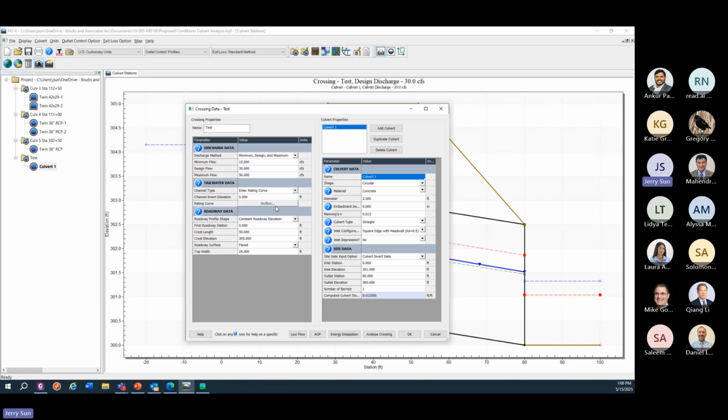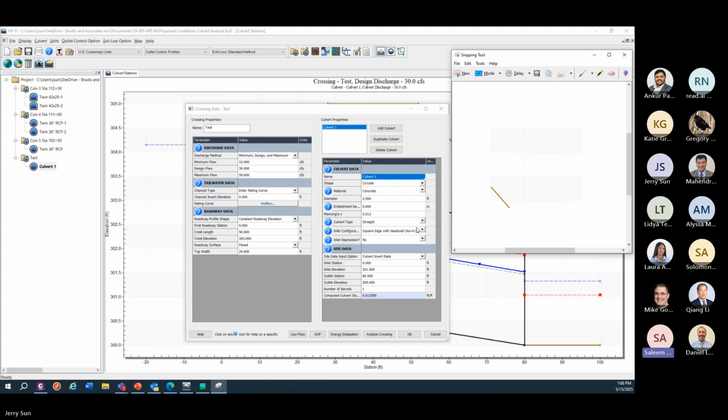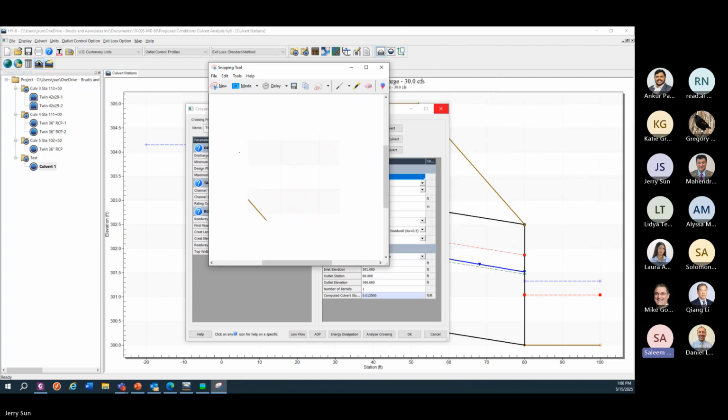A rating curve is basically used for a culvert with manholes. For example, in SNAP, maybe most people don't use it, but it is very similar to the irregular channel. Instead of a cross section, we are just entering the data: with this much head depth, we are going to have this much flow. It is again some sort of irregular, or sometimes it may be for lakes too.